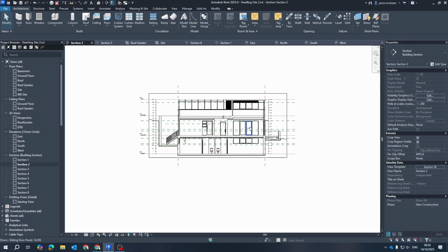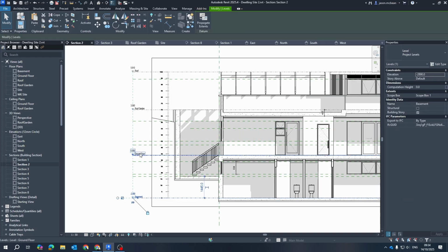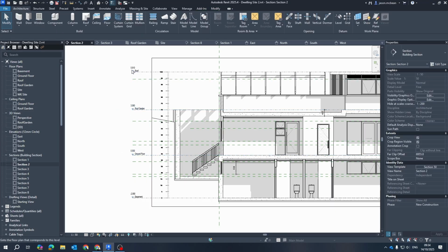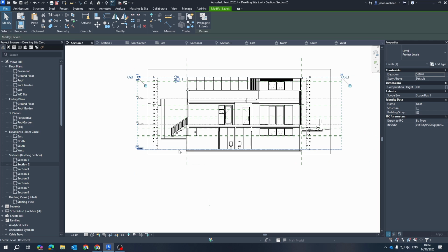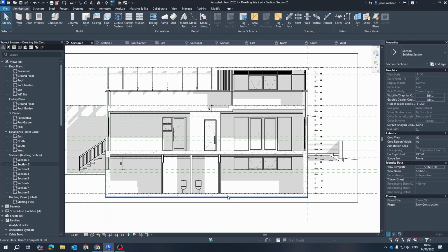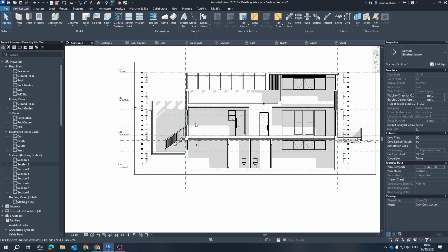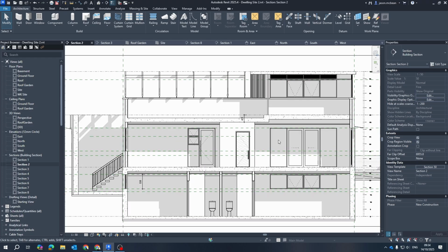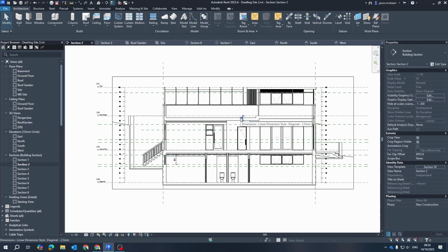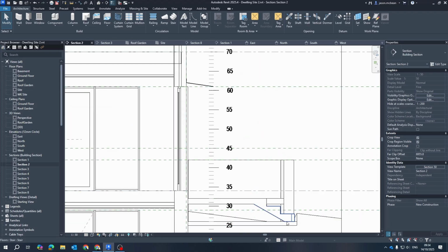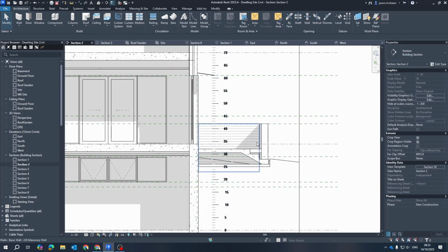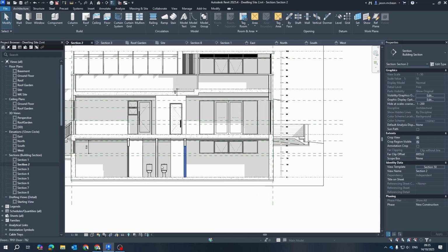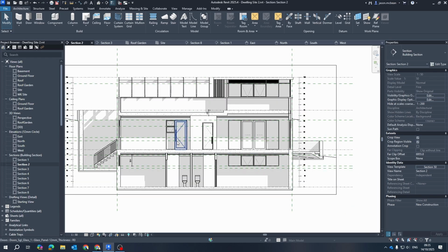But what you have to understand is that this is all driven by the levels. So getting your levels set up correctly pretty much drives the whole project. For those of you that are using Revit, I can give you some assistance, and I've got some other people to help us. And here you can see I've had to customize the stairs somewhat. Yes, the fill doesn't quite work the same, but we have to do a lot of drafting over this to get a good result.